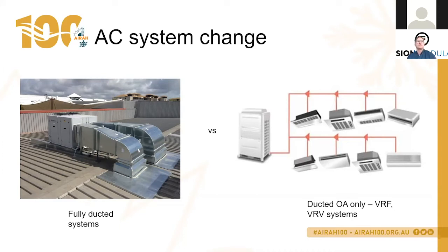direct ducted the outside air into the space for a DOAS system, or we could think of some other solutions. Because we're only considering the outside air into the space, that may now not present a problem, as we only had 800 litres a second of outside air in the case study. So that doesn't present as much of a problem going through that pinch point. We could still get a reasonable aspect ratio on our duct. So we may do that. So that's another option. You change the type of system and the arrangement.